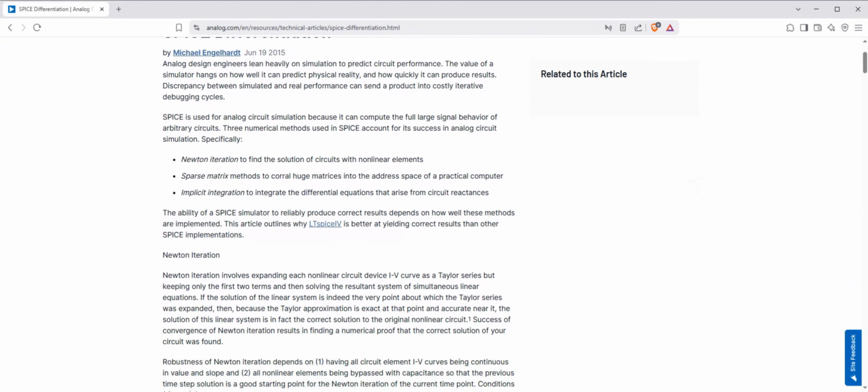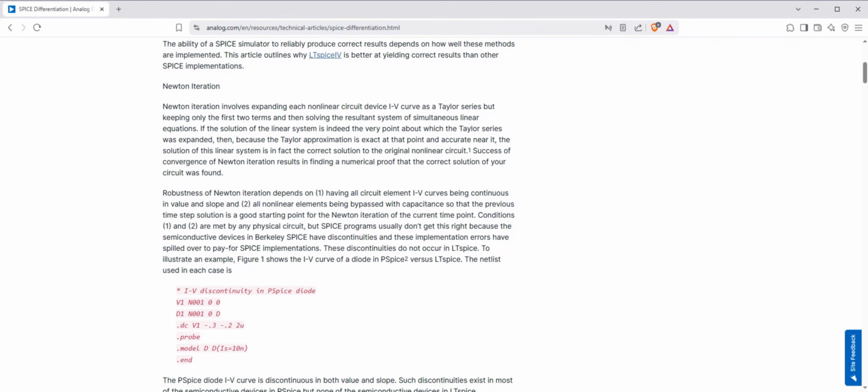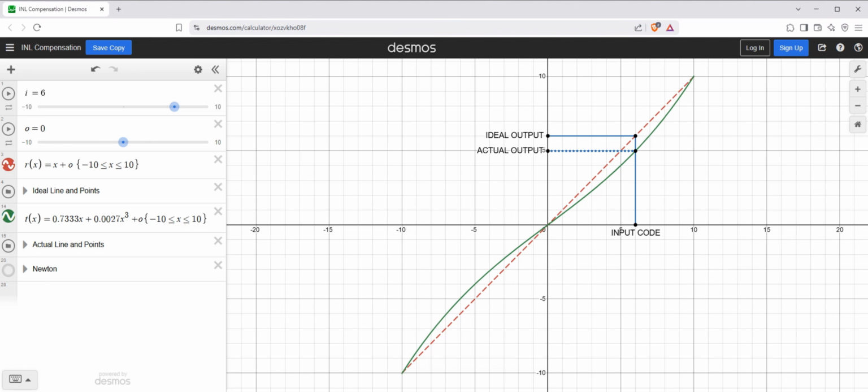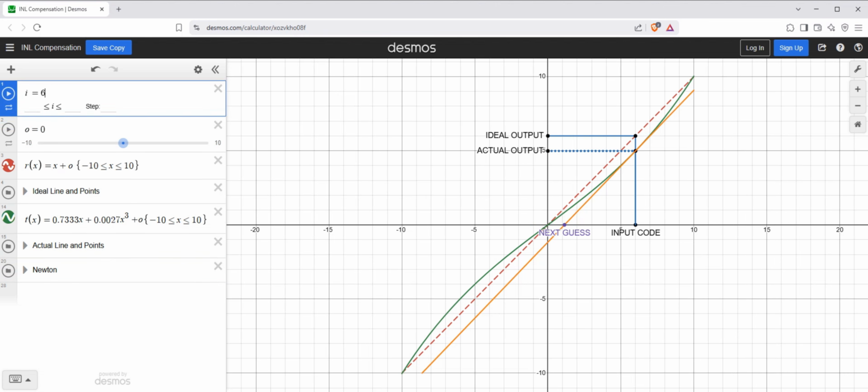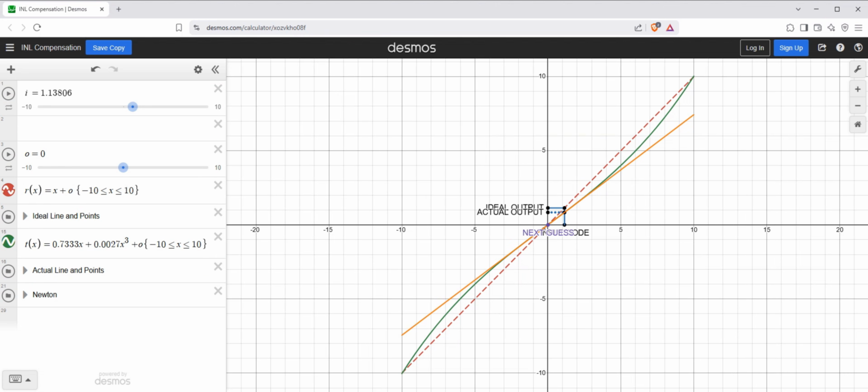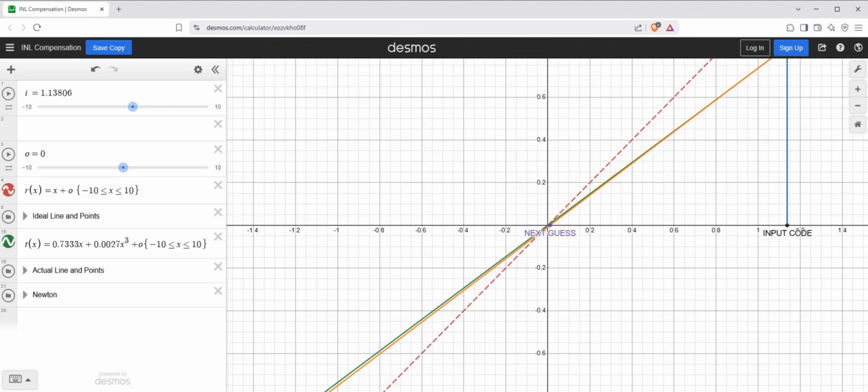The solution to this tricky problem is the same LT-SPICE uses to solve nonlinear equations. Newton's method is a root-finding algorithm that uses the first derivative of a function to successively refine an initial guess. The zero crossing of the first derivative at the initial estimate is used as the next guess. The derivative at this new point is used, once again, to calculate the next guess.